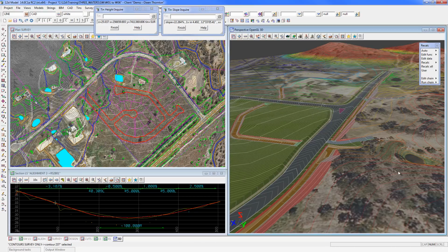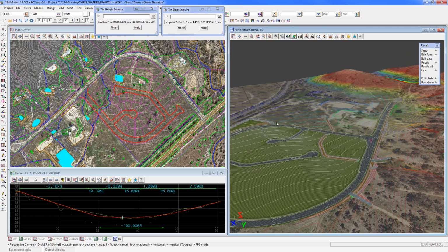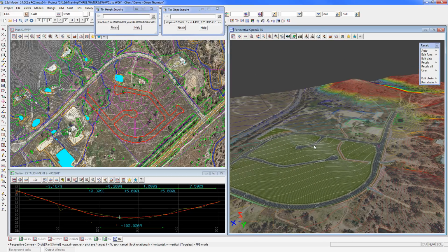But the road drainage is certainly on the downstream end near the basin. That will be separated from this runoff, and the flow rates on the roads will be an order of magnitude smaller compared with the significant amount of runoff we would expect on this particular site from these hills to the northwest of our site.